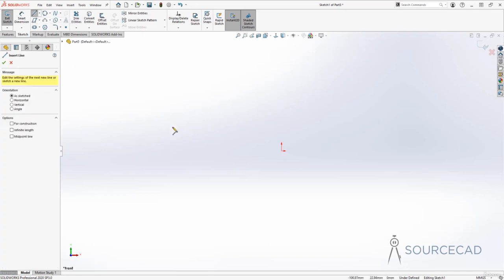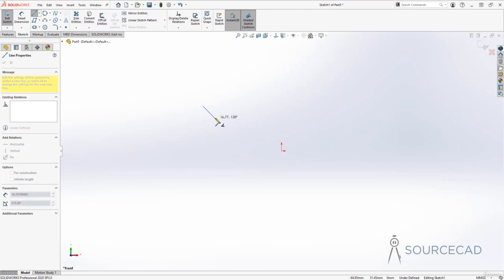Now you can start your line tool simply by clicking at a point. So click at a point and then let go of your cursor. Don't click and hold your left click. Just click, let go. Though if you click and hold your cursor, you'll still get a line, but it's not that required kind of thing. So you can click, let go, then again click again and again and again, and you'll have your lines.